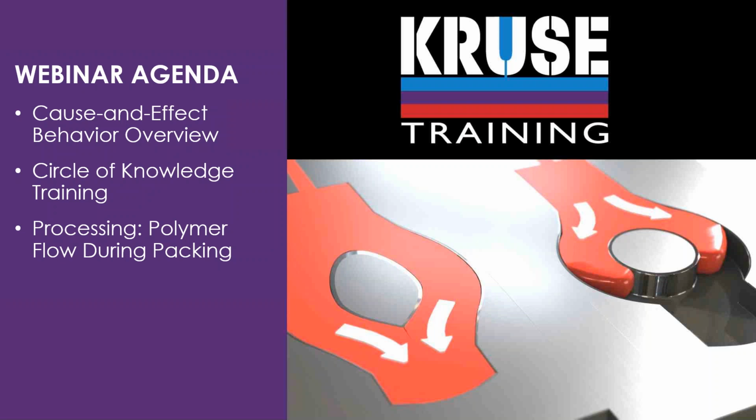This is very, very interesting subject matter. Most people overlook that, and I want to give you a quick overview of what to expect and what to look for when processing a material, and how to set up the pack, or how the pack pressure and the pack pressure profile will influence the volumetric shrinkage behavior inside of your molded part.